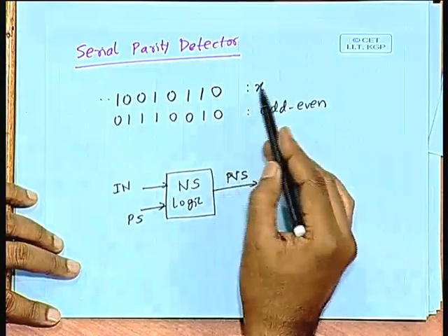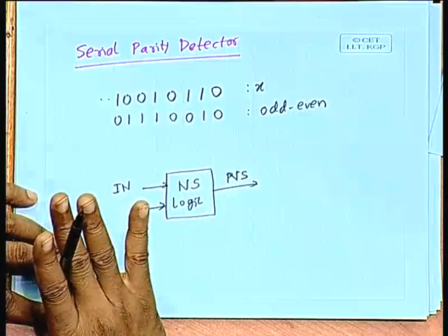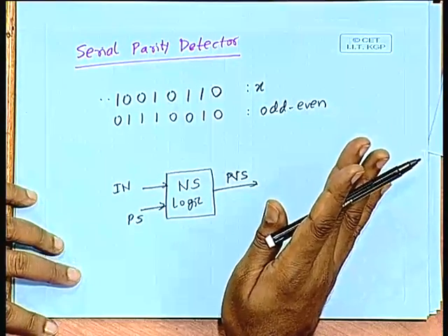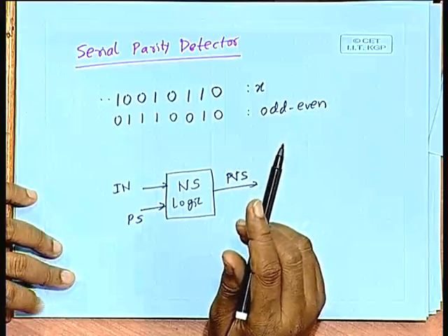For the output you do not need x, this is what I mean. So, you can categorize this as a Moore machine, it is not really a Mealy machine. The way you wrote the code, it looked like a Mealy machine. We try to mix them up, but actually the way it is working, it is independent of the input. Whatever state you are in, from the state you can directly derive what should be the output at the current point. Okay.